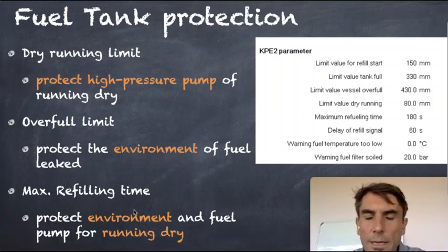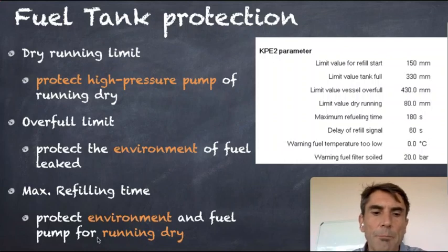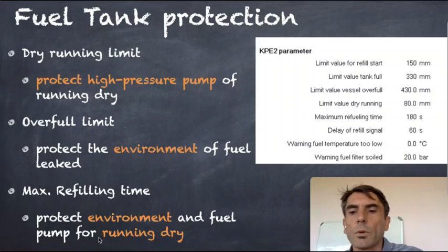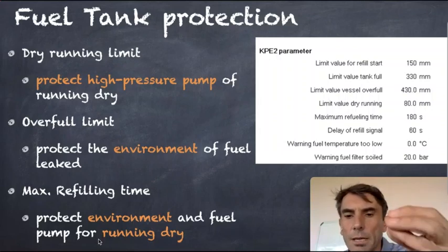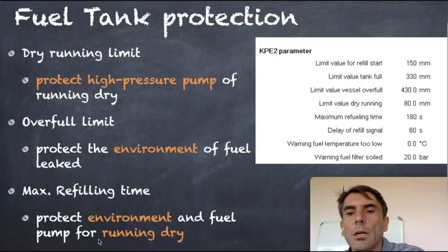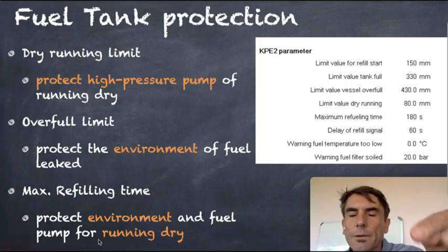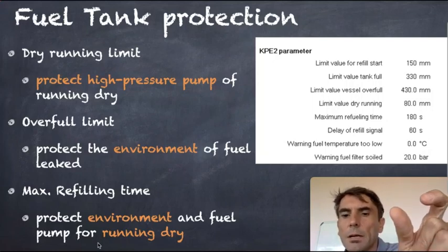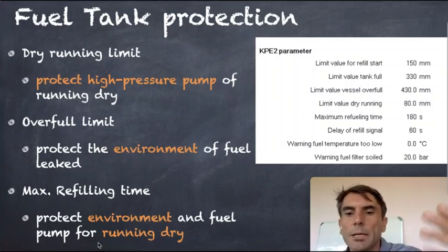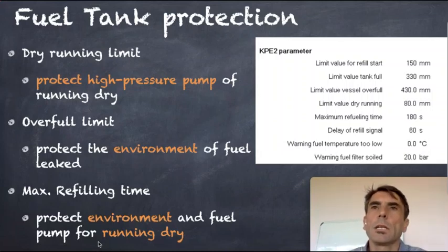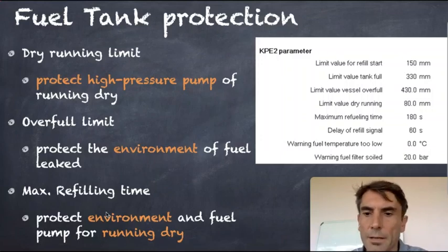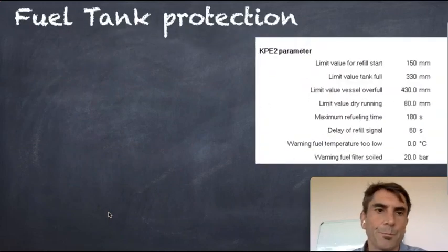And we like to prevent damage to the refilling pump as well. If the refilling pump is running dry because we suck air out of the fuel tank, because fuel tanks are empty, for example, to prevent the refilling pump from running dry, we stop after 180 seconds. If the pump is running dry, it actually gets overheated and the pump gets damaged. So we like to prevent that with this protection system.